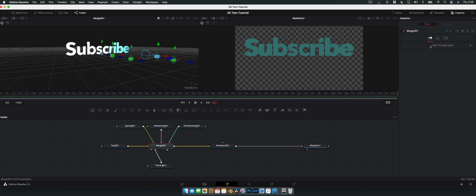Without that selected, the lights do not go through to the renderer. They sit in the 3D space, they are there, we can move them, we can see the effect on the text, but they are not completed and compiled into the final 2D image that we're getting in our media out node. So the first step is to select that merge node and hit pass through lights. Great, we've done that. We're still not seeing anything.